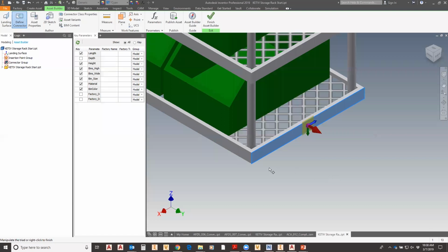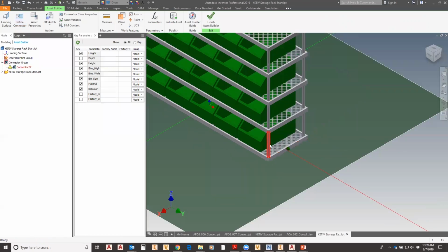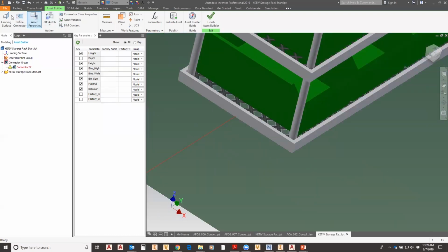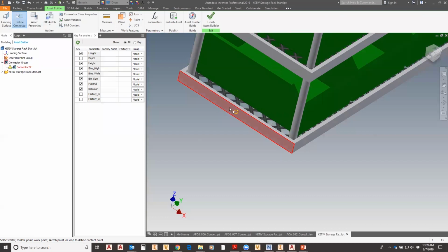okay? And so again, the red is already pointing away, right? And I can go ahead and tell it that up is in this direction, and I've got a connector. Okay, so I'll click OK. Connector on one side, connector on side number 2. Okay, it will snap to the vertexes as well as that middle face. Okay, so red arrow, beautiful, it's already in the right direction.